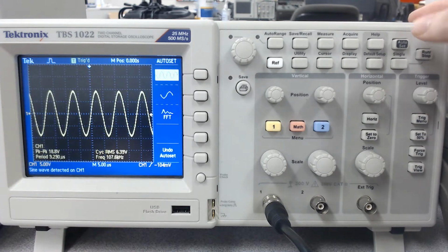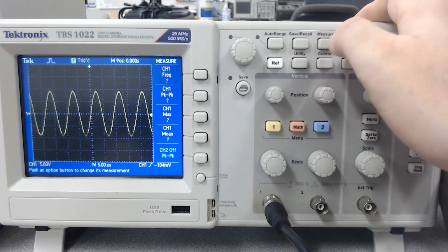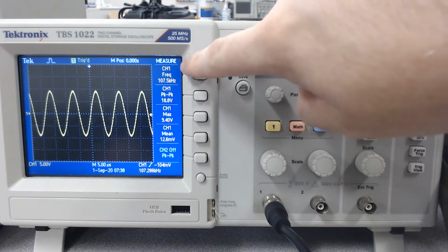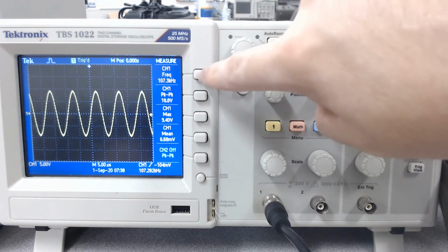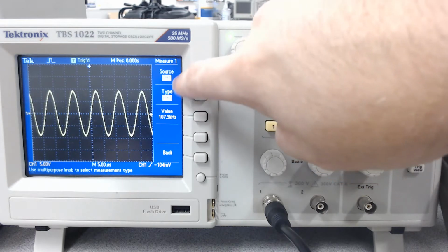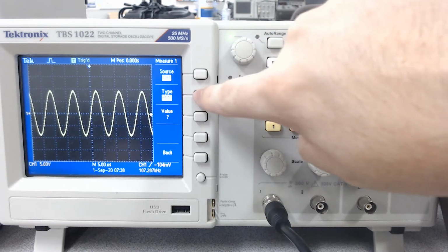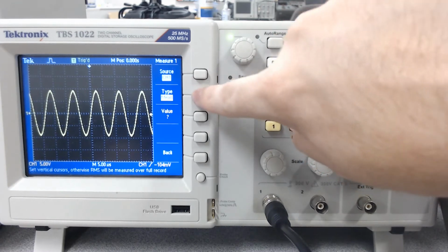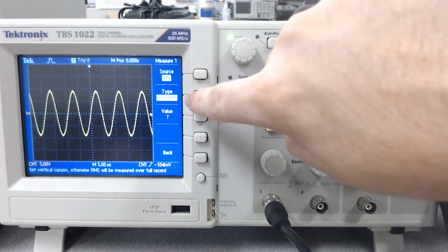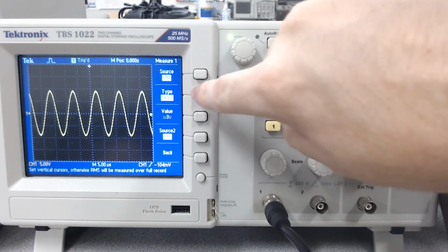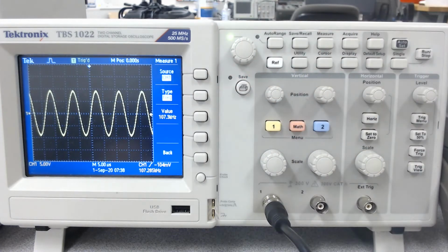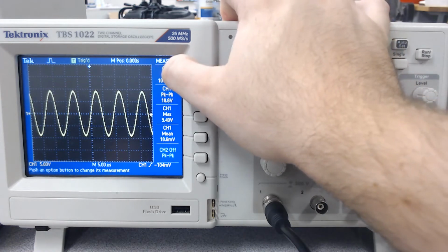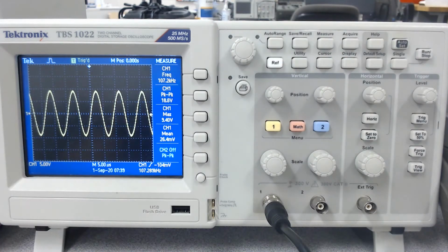If we wanted to measure things, what we could do is hit this button, measure, and set some of these to what we want. But obviously the easiest way, it's actually already set for you, but if you hit the button next to it for frequency, you can change it from channel 1, you could change it from frequency. We're going to cycle all the way around and hit frequency as well. It's kind of sticky. These things move a little slow, so you want to make sure you don't pass it, because that's actually what I just did right there. So we have frequency showing, you can hit back. That's how it was, with channel 1 and the frequency reading right there.